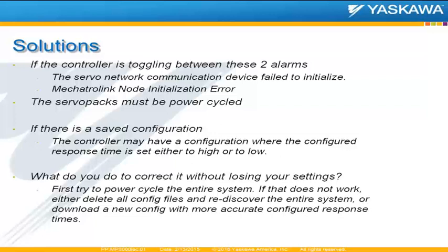If you have a saved configuration, then the configuration most likely has a response time that's set either too high or too low. So what can you do to correct this? First, try power cycling the entire system. That's always the easiest option. If that gets you out of it, good. If that doesn't, then you either have to delete all the config files and rediscover the entire system, or download a new configuration with more accurate response times configured.